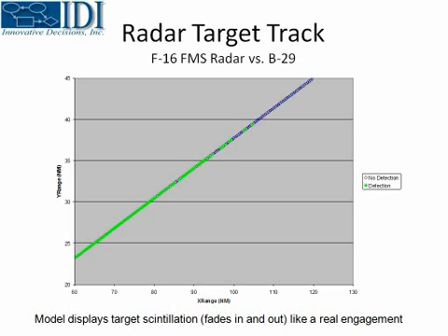But the target will fade in and out because it moves in and out of those spikes. As you get closer and closer, you'll get more and more hits, until you're getting hits almost every time, but there are some really narrow areas where you get very little return because the radar cross-section is low, until you finally get in close enough that you get a hit every time because there's enough energy coming back. That's very realistic of what you would see in a real air engagement.